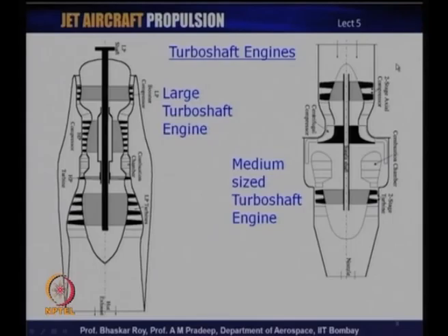The rotors also typically run at very low speed, like the propellers, quite often even lower speeds, maybe even less than 1000 rpm, and these rotor sizes are much bigger than that of propellers. The rotors can be as big as 8 to 10 meters in diameter, and as a result their rpm would have to be somewhat restricted for various structural and aerodynamic reasons connected with the rotor motion.